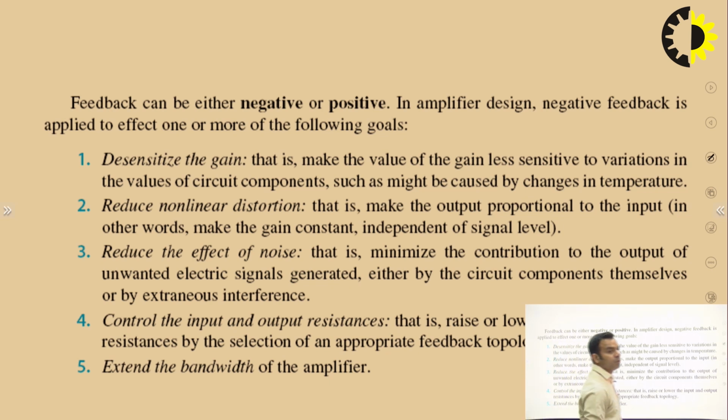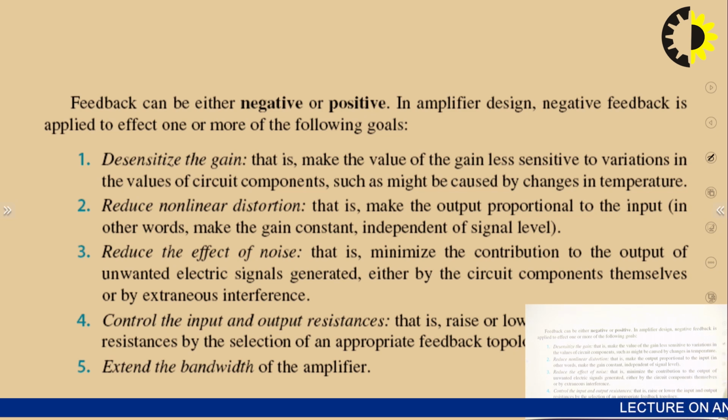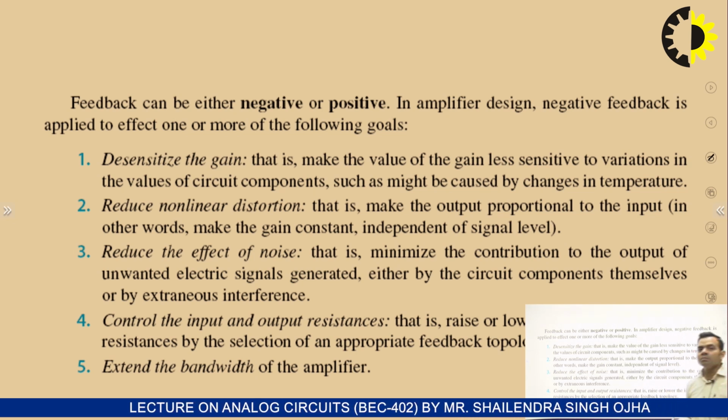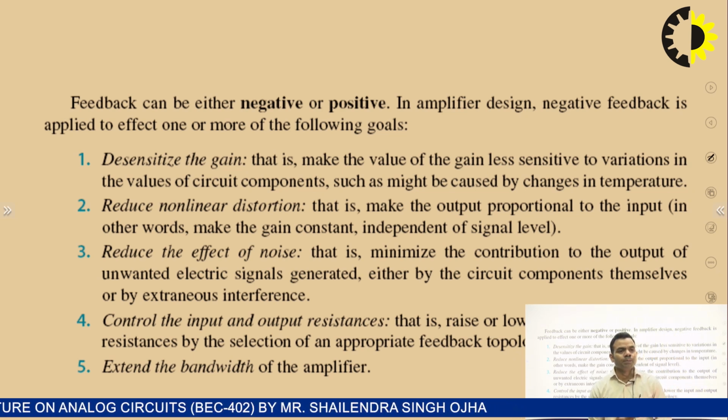These are few more advantages, like it desensitizes the gain. That means it makes the value of gain less sensitive to the variation in the value of circuit components, such as might be caused by change in temperature. That means various components' values can change with respect to temperature, so it will desensitize the gain. Second is reduce the nonlinear distortion. This is another advantage. One more advantage, reduce the effect of noise, control the input and output impedances. Actually, you can achieve the required resistance, either input or output. Very soon we will see how we can control the input and output resistance.